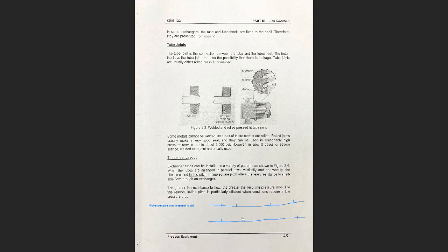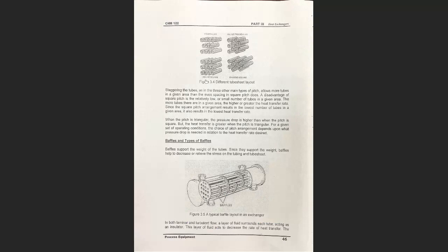Of course, guys, the fewer pumps, the more profitable for you. Why? Because operating costs will be lower. Pumps run on electricity and consume more electrical energy, they need more spare parts, and they need more maintenance work, and mostly, guys, more maintenance means more employees, so the financial gains will be lower. So in some situations you don't want high pressure drop, and that's why this kind of layout or pitch is preferable when you want to avoid very high pressure drop, which is the inline square, the third one here.